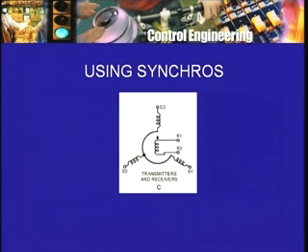I mentioned a device called a synchro, and I said that these come in pairs, and so you really have two synchros. One is connected to the telescopic sight and the other synchro is connected to the gun. The synchros produce voltage output, and it is these two voltage outputs which can be then taken, compared, and any action that is necessary